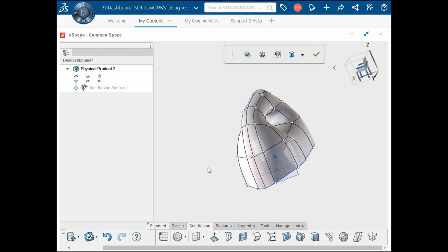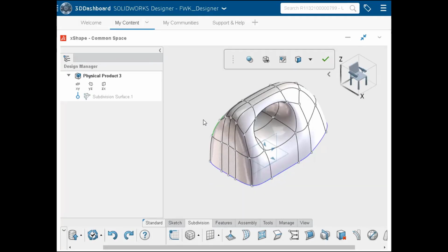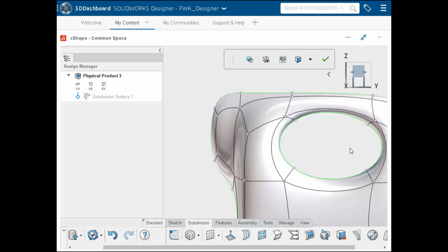After making a few more adjustments, we'll use Extrude in a different way with a different toolbar. Control-select the two rear faces and then click Extrude from the Quick Command toolbar. An extrusion combining the two faces is added. Here's another great option, aligning a set of vertices. After adjusting the extrusion, box select vertices and click Line Align from the Quick Command toolbar.